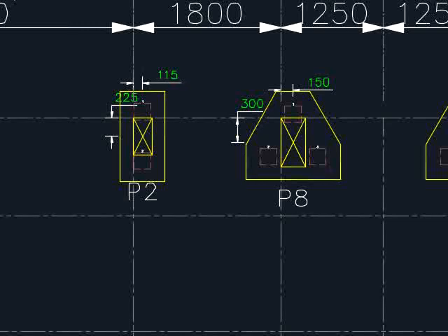That means you now have three centers that must be in the same location: the center of load from the column, the center of gravity of the pile cap, and the center of reactions from the piles. They should be in line. This is to ensure the structure is stable and there is no eccentricity of the load.